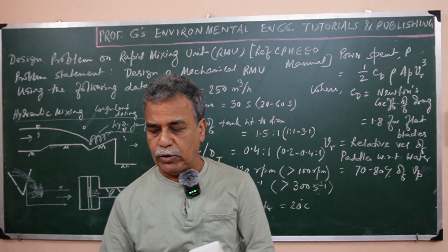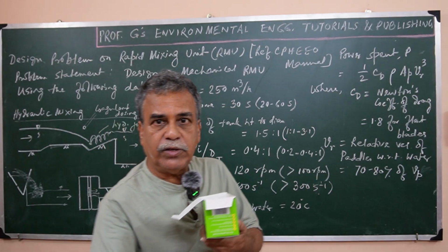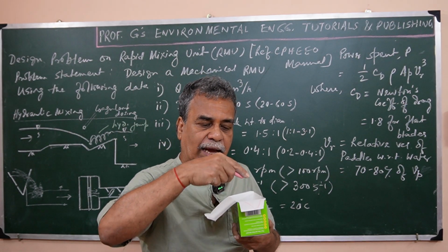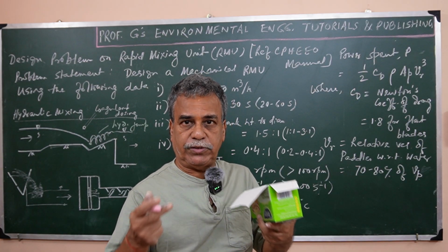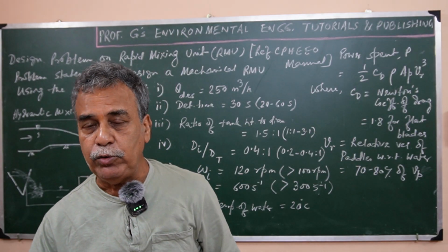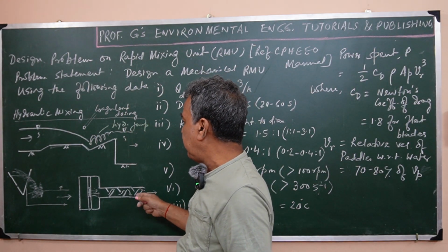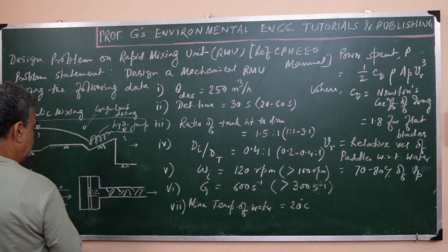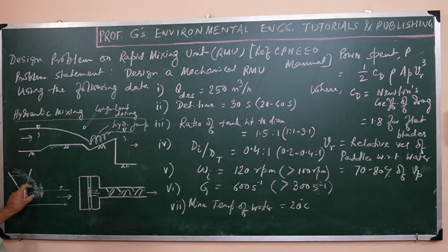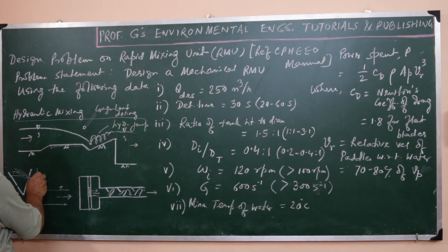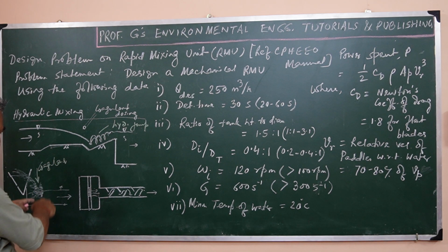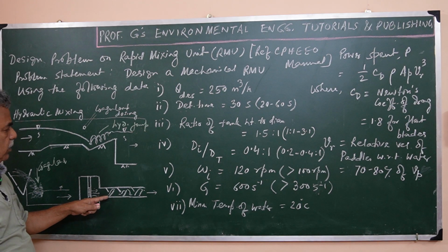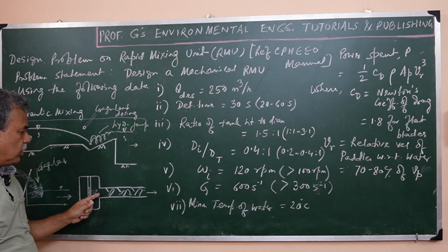When it falls down over an open channel, just below the jump where it falls down, there will be turbulence, and we can use that turbulence this way also. Following that, the turbulence will be here, and the coagulant dosing will be done here.